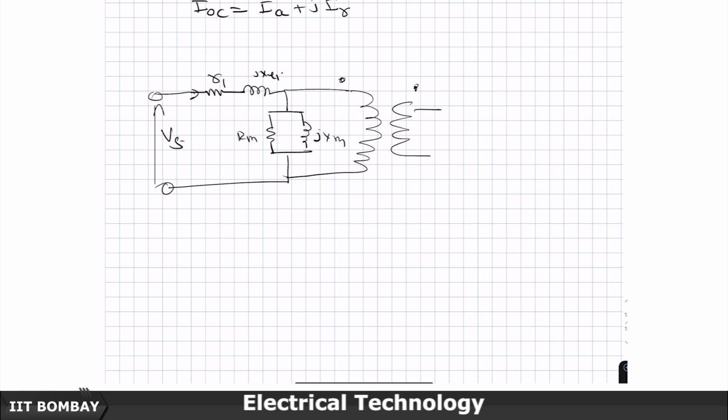So, what happens is a very small drop will happen in the resistance and the leakage. This is not going to be a predominantly big drop. If this is a big drop, then your transformer device will not be very close to an ideal device. We will engineer the device in such a way that these losses are small. So, we will usually have thick enough wires, so that the resistance is small, and the whole idea of developing our transformer was to keep the leakage inductance low. This is at this point of time more like a parasitic effect. So, a very small value will be there.